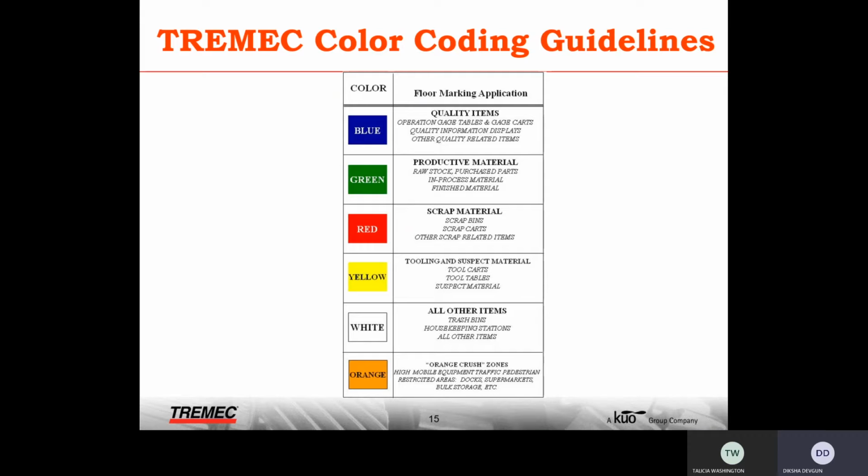So green tags are used for good parts only. Green tags will be used for parts that are ready to be reintroduced back in the line, or reused in terms of gears or shaft. Red tags will only be used for the scrap parts. The parts that we cannot reuse or the parts that we definitely will be scrapping are all red. Yellow are all non-conforming or suspect.